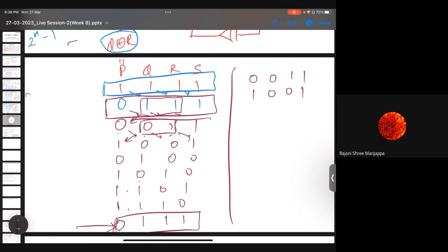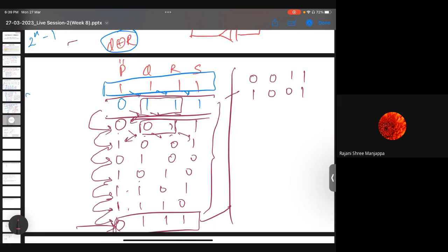Can you understand this? We had 0, 1, 1, 1, and now it is getting repeated after certain cycles. Is it fine? Yes, sir. So we are never getting 1, 1, 1, 1 again, but we are getting a circular period and the same bits again. You can check 0, 1, 1, 1 and 0, 0, 1, 1 getting repeated. So you can check the number of cycles: the first clock, then second, third, fourth, fifth, sixth, and in the seventh clock cycle we get the repeat. Is it fine?